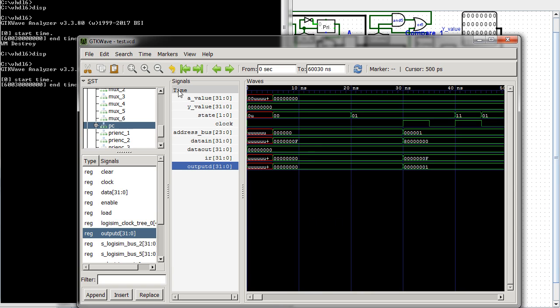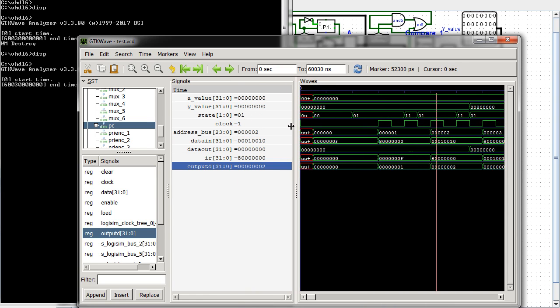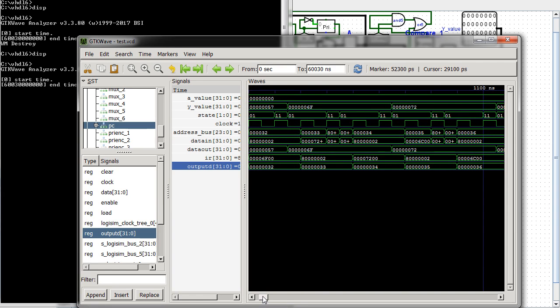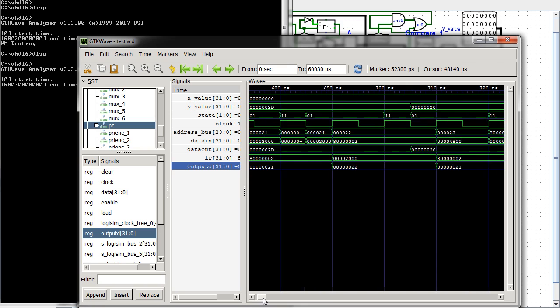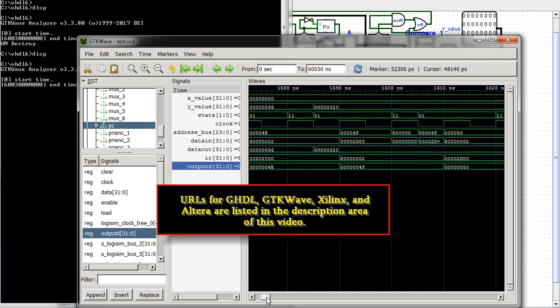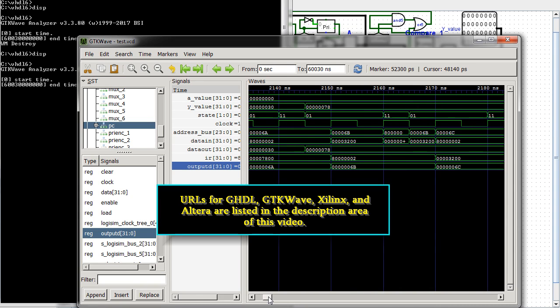From what I read, getting a design to be ready to be put in an FPGA involves a little more work. You have to deal with whatever gate delay timing issues or other timing constraints that might arise, as well as any peculiarities of the particular FPGA board and other design issues. You might need to use the specific software that came with your board to work those out. By the way, both Xilinx and Altera have free scaled-down versions of their software if you want to give those a try.